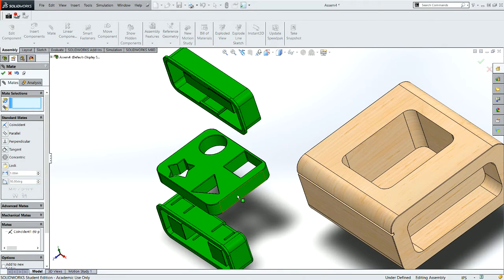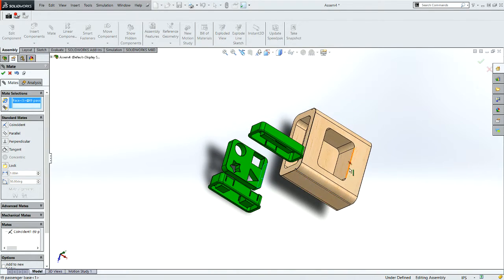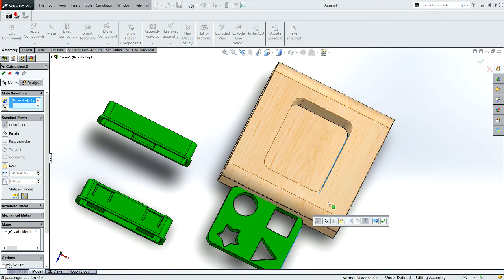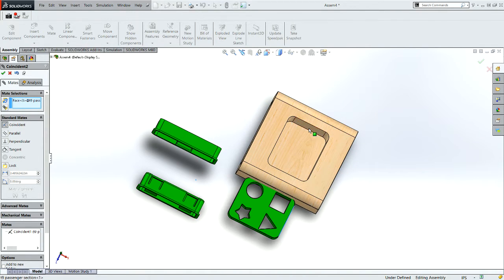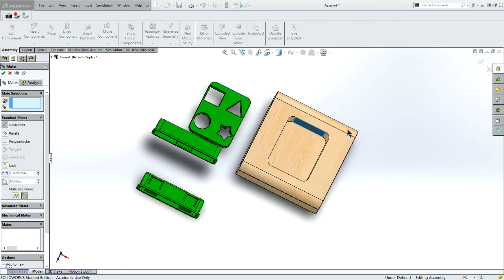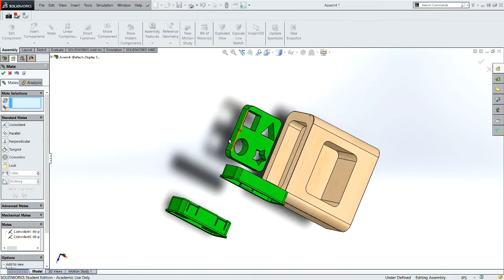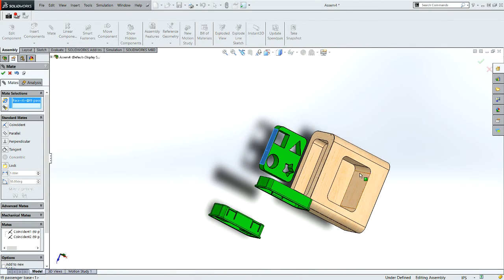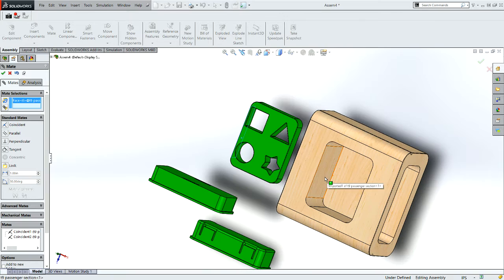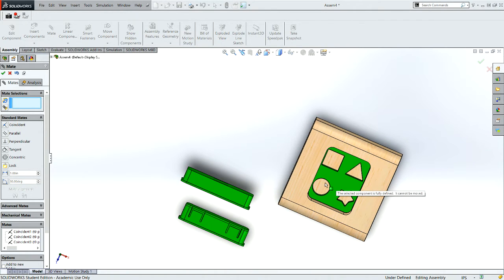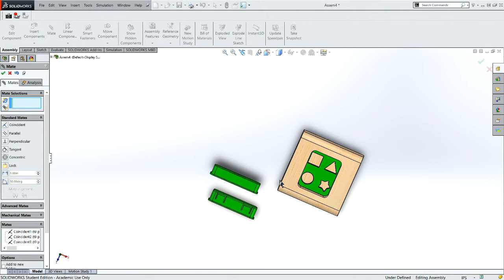I'm now going to put the front of the passenger section onto the front. Oops, I've got that actually wrong, so this is a good experiment here. I can come back and delete that last selection. I want to actually orient it that way and accept that, and then I'm going to choose the back side of this passenger base against this wall right here. And there my passenger base is fully defined and fully locked in.